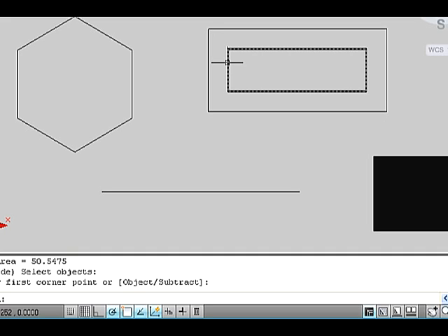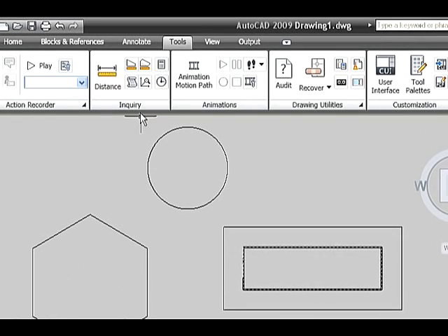Let us see the next sub-option, Subtract in Area command. Note, we should select the major area by Add method. After that, only can we subtract the required area from them. Subtract. Go to the Tool panel and select Inquiry tab. Now, click on the Area command.